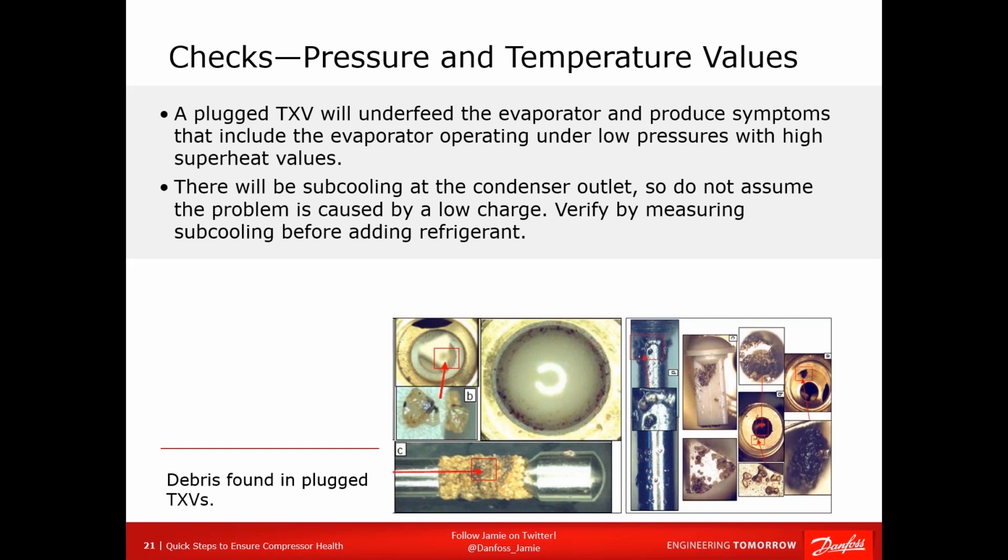And you get to the question where you have 24 volts or 26 volts at the control transformer. And you go to the compressor relay coil and there's 0. Well, you don't automatically put an extra transformer in there and double the voltage just to hope it gets to the relay. What do you do? Well, you go and figure out where the voltage went.